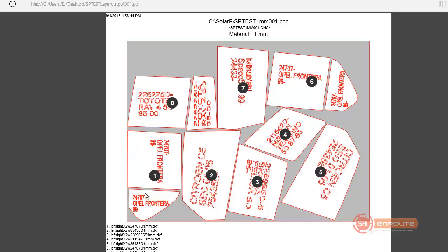Now, I group these two together as one part. And here you can see part 6 and part 1. These are related to 2 different parts that I did as a single piece. If we wanted to separate those, we could. I was just not sure if they would be or not. Sometimes, if you had 2 parts that fit together really well, you might want to do a pairs nesting instead of nesting a single part. And so that's kind of what I did here. I nested these 2 together as a single part. So we might break those up and get a little better result.